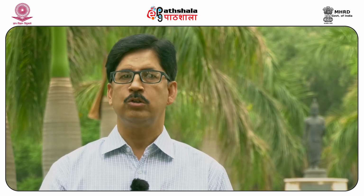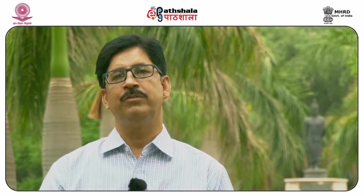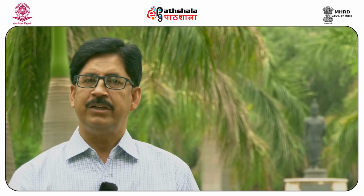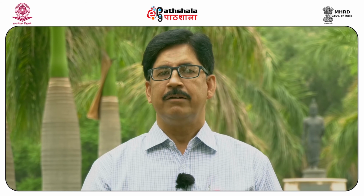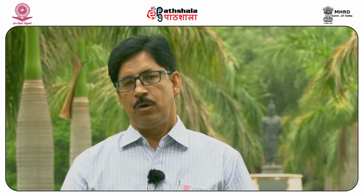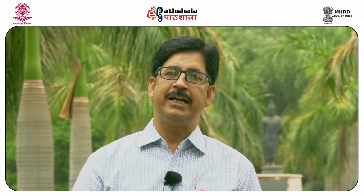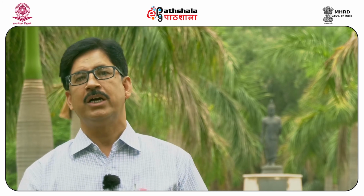Along faults and fault zones we also get mylonites, gouge and breccia of different thickness and lengths. We have to excavate them and backfill with concrete, because they are going to be very detrimental for any civil engineering structure, be it a road, a railway track, the foundation of a dam, or a tunnel across them. When we come to faults, depending upon the wavelength of faults and the length of the structures, we have to see what part of the faults we are working in.